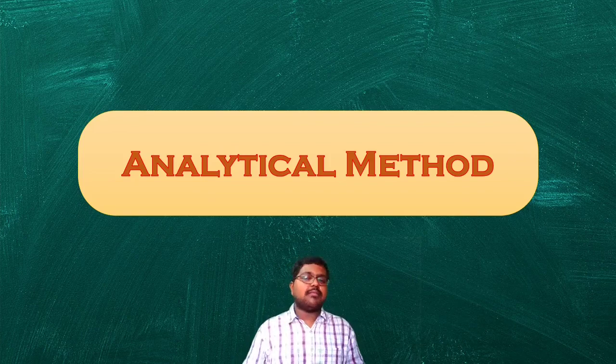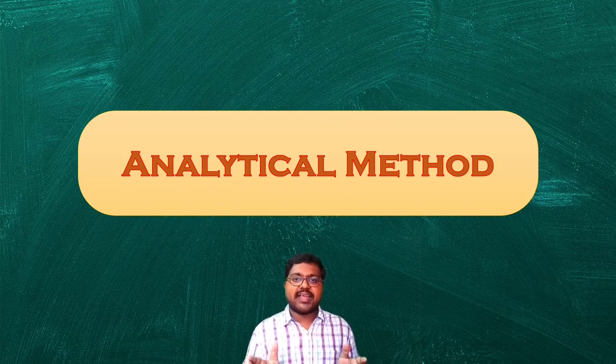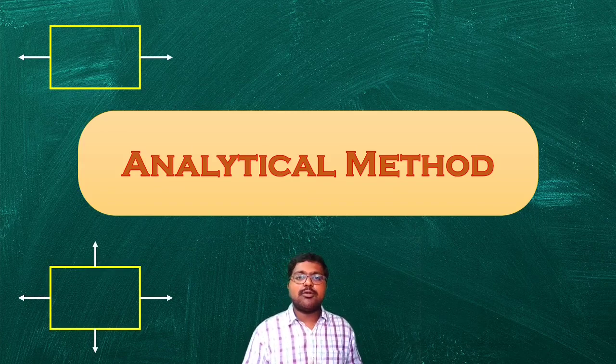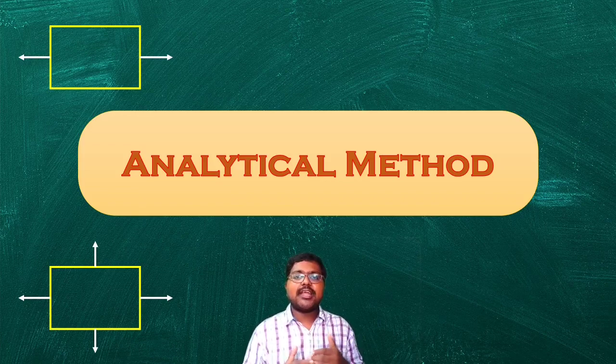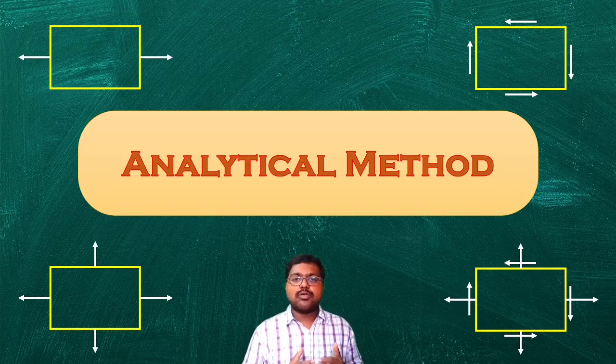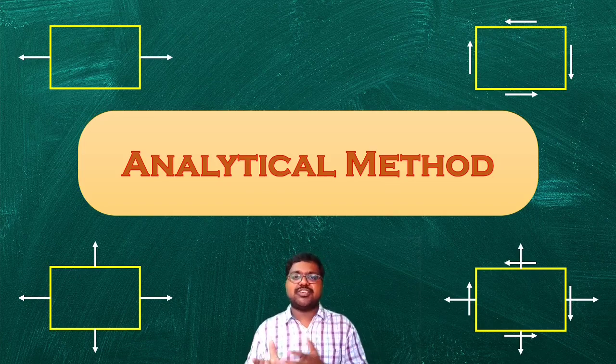If we see the analytical method, it is divided into four different cases, where case 4 is a combination of all three, but for our easy convenience, we separated it into four parts. The first case is a member subjected to a simple tensile force, and the second case is a member subjected to simple tensile forces, like direct stresses perpendicular in nature. The third one is a member subjected to pure shear, and in the last case a member is subjected to two direct stresses which are perpendicular to each other and accompanied by a shear stress.